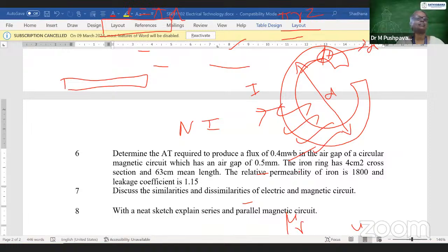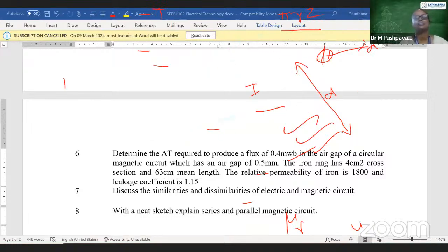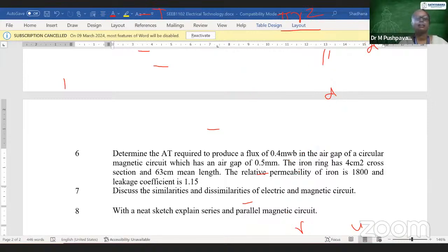Take down the answers alone, and check it. Ampere turns is 1400 ampere turns. Total reluctance is 0.103 ampere turns per Weber. And check the flux value and flux density value, whether you are getting the same answers. The leakage coefficient formula also you may try. All the best. First unit, I think I have been sharing that again.